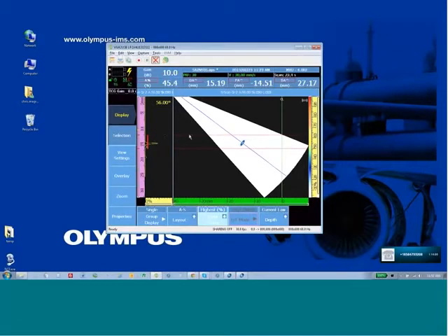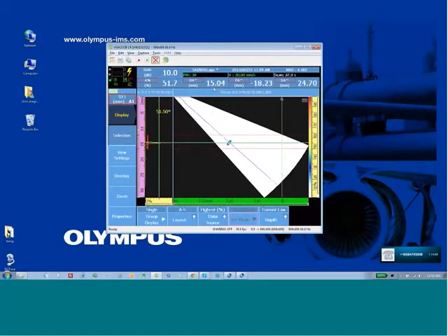If you can maintain the signal at the correct depth, and in this case it's 15 millimeters, across the entire sector scan prior to calibration, this right away is an indication that the velocity of the wedge, the velocity of the component, the probe and wedge parameters such as pitch, height, wedge velocity, wedge angle, it's an indication that all of those are correct.